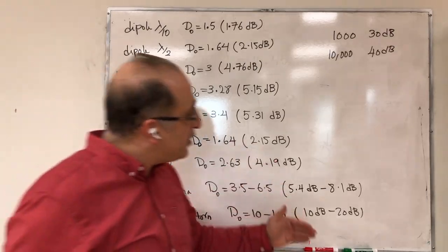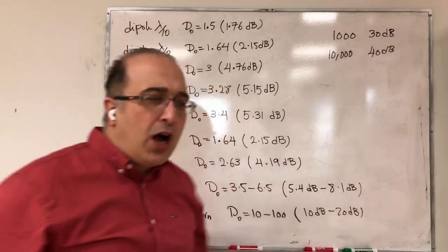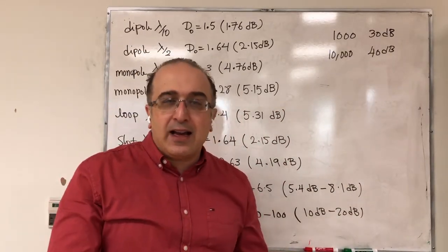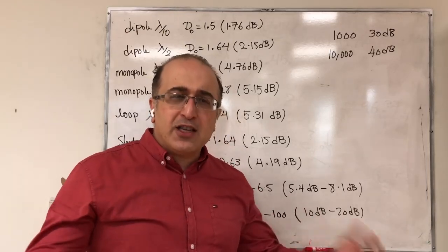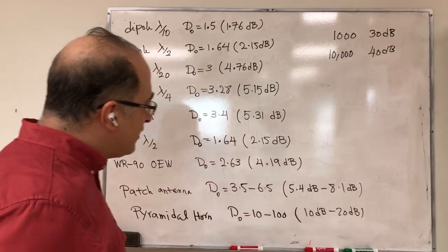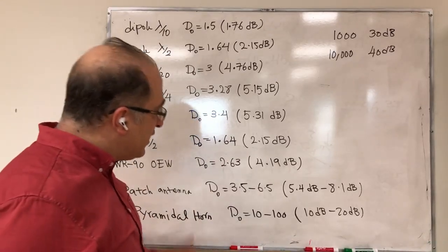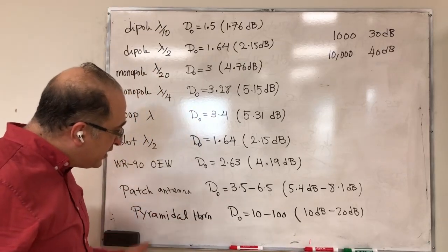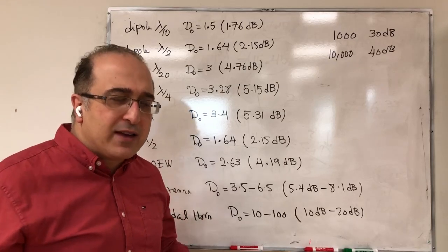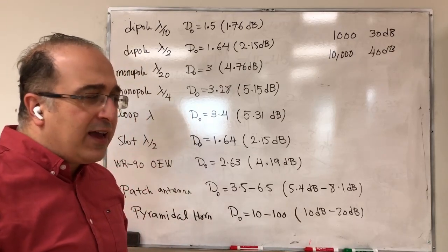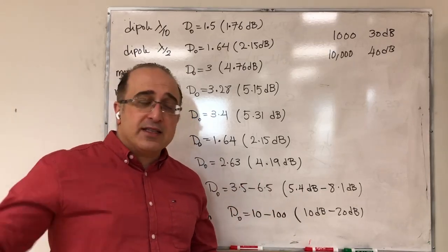So in this discussion, when I'm saying I want to increase the directivity, let's say to 10,000, I mean using a single antenna element, not multiple antennas, because that also has complication. For example, if you are to use multiple horn antennas, you remember we had an approximate formula to estimate the directivity of the antenna array, and that's just completely an approximation under certain assumptions.